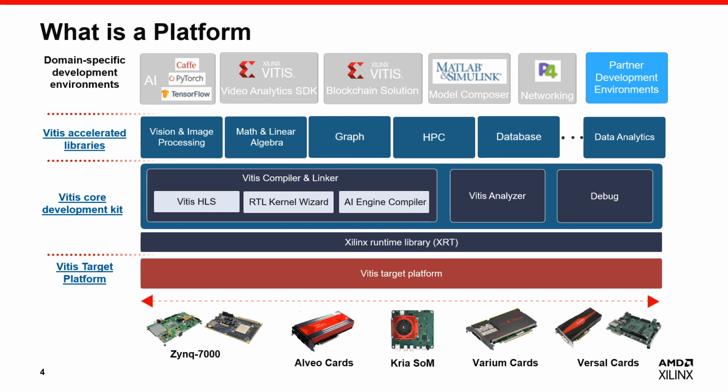There are differences between data center use cases and embedded use cases, because in embedded use cases, we need to provide the embedded operating system and components. The target of the Vitis development environment is to help developers focus on their application development. So we package the operating system, XRT, boot components, and target hardware design all into embedded platforms.